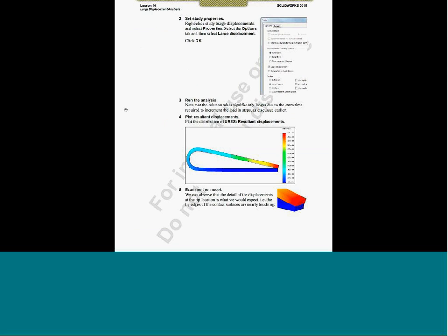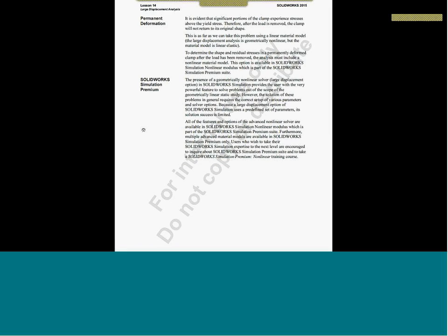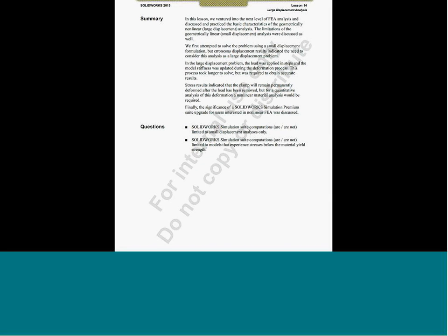So here it goes. Let me quickly scroll through the training manual to see if there is anything important that I have left out. As per the training manual, Solid simulation computations are limited to small displacement analysis only. So this is a fact. It is limited to small displacements only, and models that experience stresses below material yield strength. Yes, that is also true. I think these two topics are well understood now.